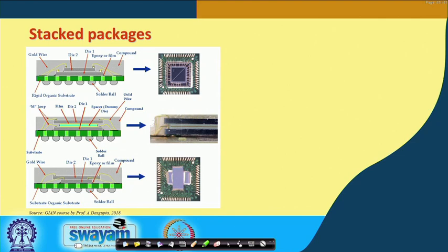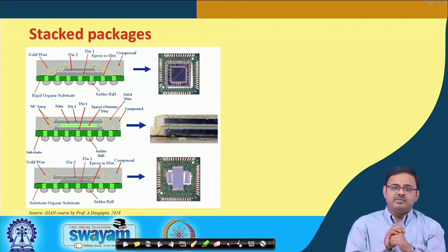I am just telling you some of these research challenges that come because of these stacked packages. So, thermal design of stacked dies is also a very, very important parameter. Of course, coming up with the packaging technologies, how to do it, etc., is very, very challenging, but thereafter it is not just electrical connections, but even the other consequences that one must remember.